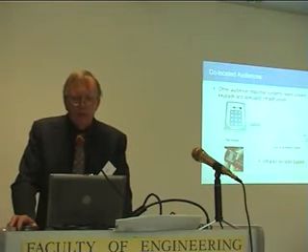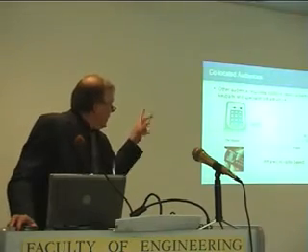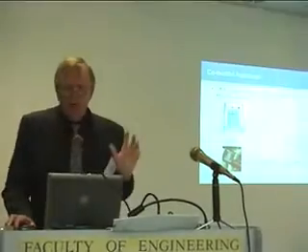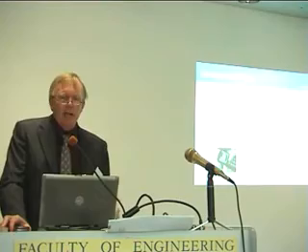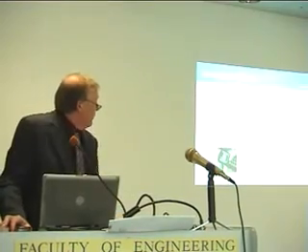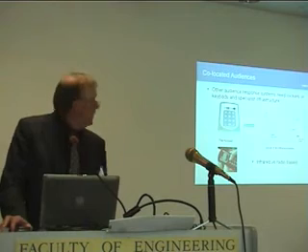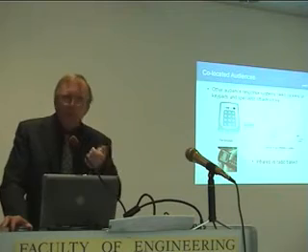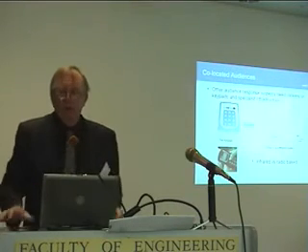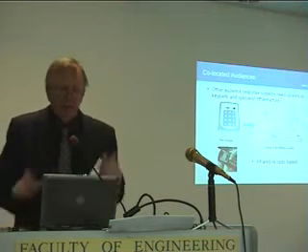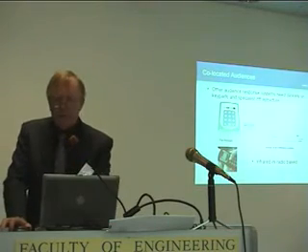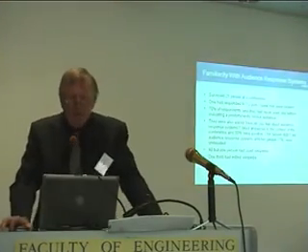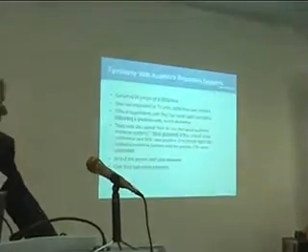These sort of systems aren't new. They tend to be either infrared or radio based, and here's a couple of the commercial systems. But you've got to put in some special infrastructure. Everyone's got to have a keypad. Those infrared ones, which are like a TV remote control, are quite cheap, but they don't work in a large group because infrared works fine when there's one person doing it, but if you all fire at the receiver at the same time, you get interference. The radio ones don't have that problem, but they cost a lot more. It makes it easier if you don't have to have those things.